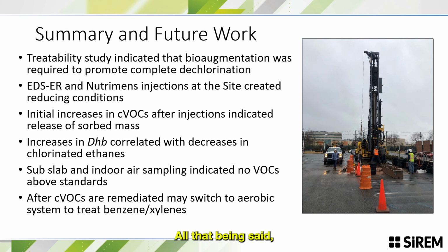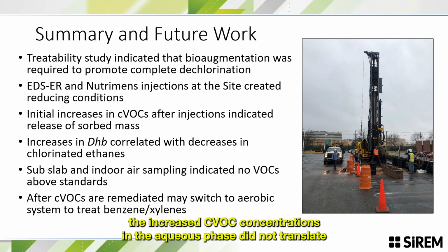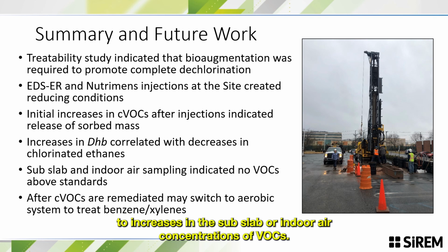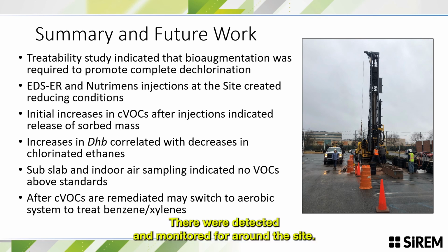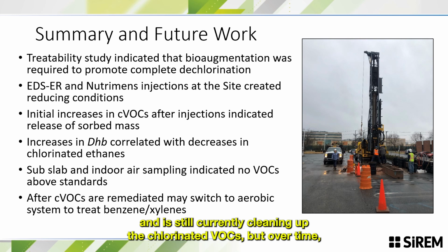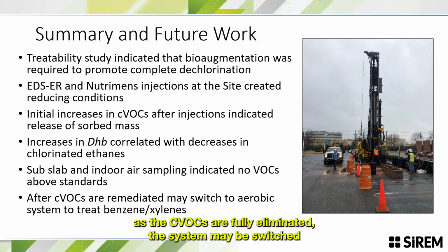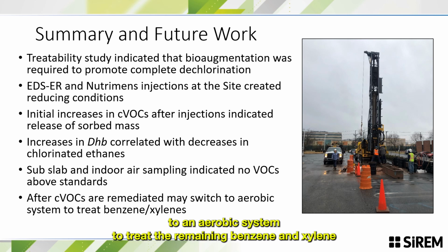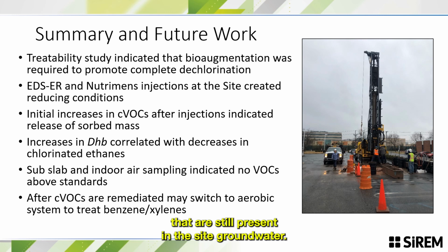All that being said, the increased CVOC concentrations in the aqueous phase did not translate to increases in the subslab or indoor air concentrations of VOCs that were detected and monitored for around the site. This site is still currently under remediation and is still currently cleaning up the chlorinated VOCs, but over time, as the CVOCs are fully eliminated, the system may be switched to an aerobic system to treat the remaining benzenes and xylenes that are still present in the site groundwater.